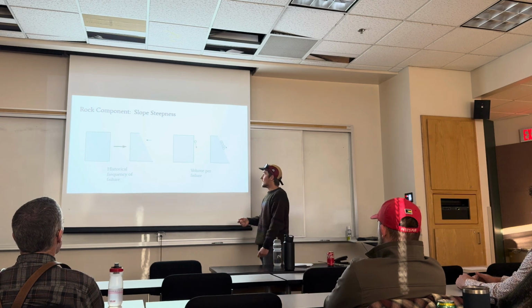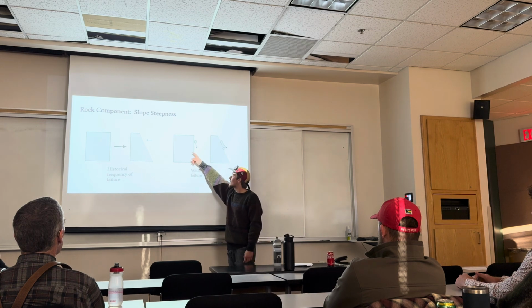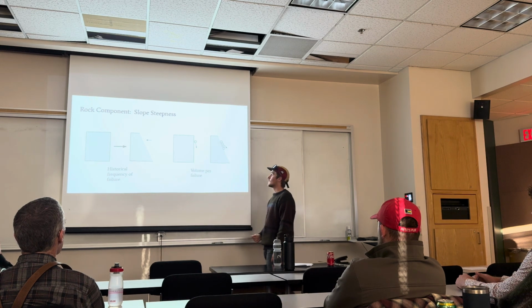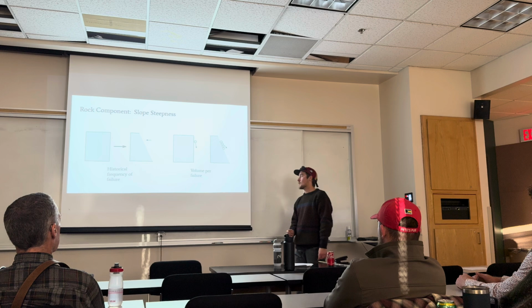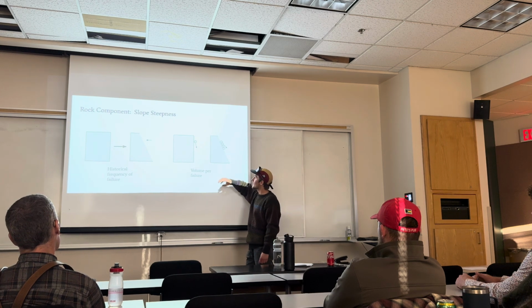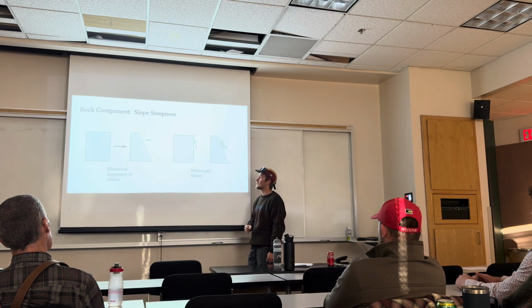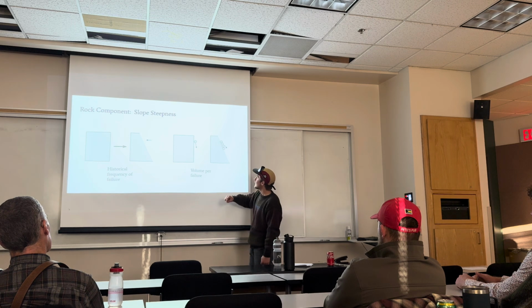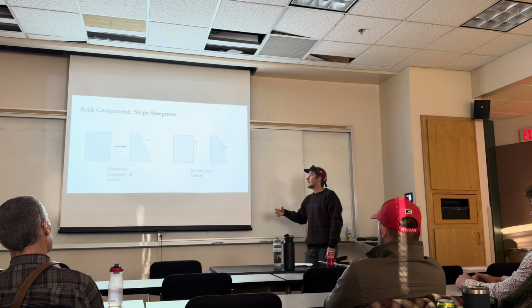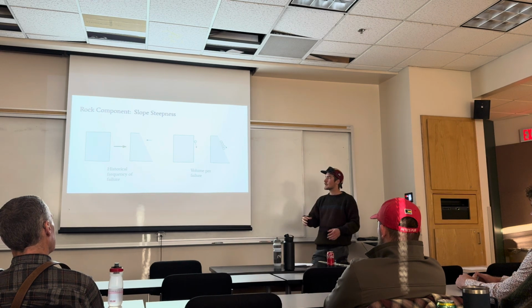Now about volume. If your slope's too steep, your rock class will weather off, and the second they weather, they're going to be transported down the slope. If you have a slope that is closer or below even the angle of repose of that lithology, it allows rocks to weather off, become loose, and build up and accumulate on the slope before the complete failure.